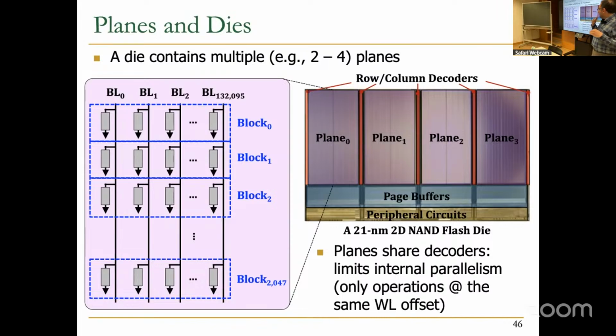But actually, there is also another command that we proposed in our recent paper, actually not very recent, MICRO 2022, if that's recent, Flash-Cosmos, where we developed multi-word line sensing. With that, you can sense multiple pages intra-block and also multiple pages inter-block. And with that, you can do computation. For example, if you activate 2 pages in one block, you are doing an AND operation of these 2 pages. But we don't have time to discuss it today.